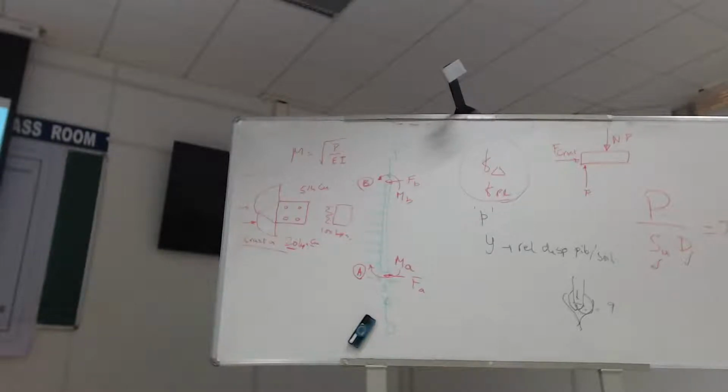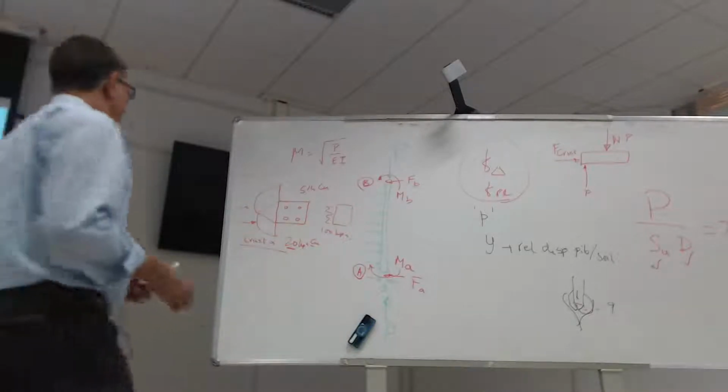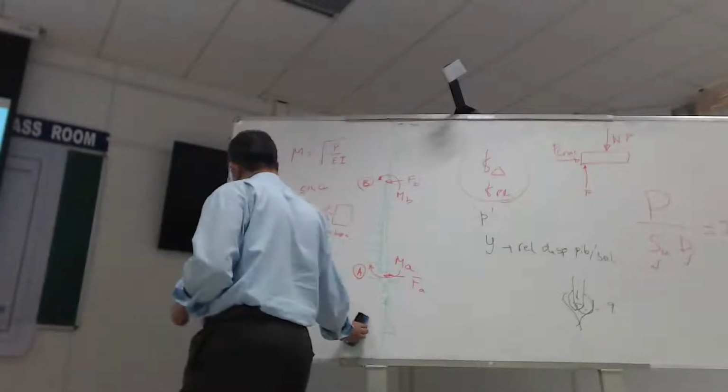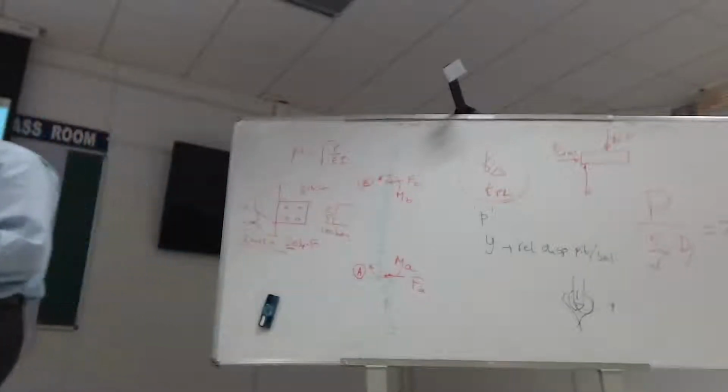Easy. So if the soil is weak and we know it fails, this is easy. If it is structural failure you're expecting, then you'll do a similar calculation. Your horizontal force will come enormous. You'll work out the shear capacity in each of your piles and see whether the shear capacity is there or not. And you'll find it isn't there, therefore that's where it's going to fail. So that's just design decisions you can make, all coming from fairly robust and simple thinking.